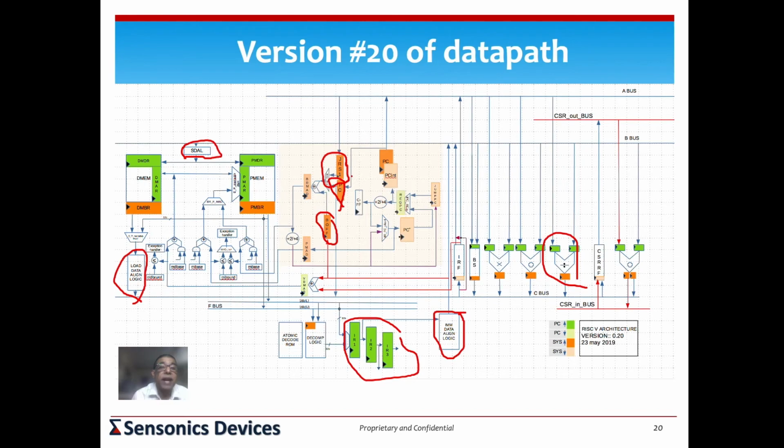and this one gets added to the base and then compared against the bound and so on, and becomes the program memory address register. The same value also goes round in this cycle, whether it's a 16-bit instruction or a 32-bit instruction, with suitable increments and all that, and they are kept in here. Various other versions of this are kept here, so they can be used for the ALU and so on. The registers that we spoke about, all these register transfers.